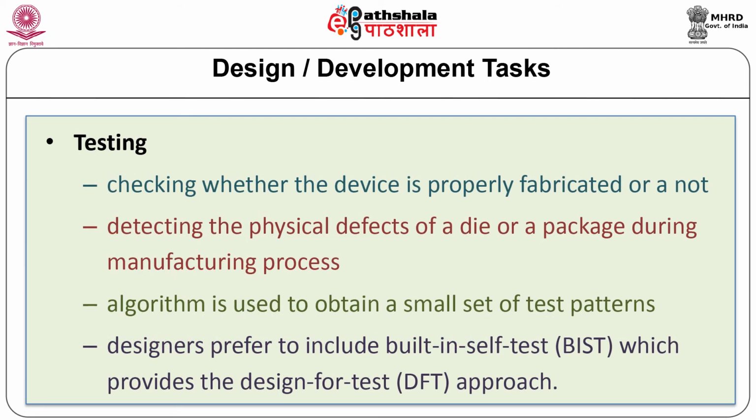Testing is the process of checking whether the device is properly fabricated or not. The course of action also includes detecting the physical defects of a die or a package during the manufacturing process. Due to the large number of inputs, an algorithm is used to obtain a small set of test patterns. Further, many designers prefer to include built-in self-test, that is BIST, which provides the design for test, that is DFT, approach.